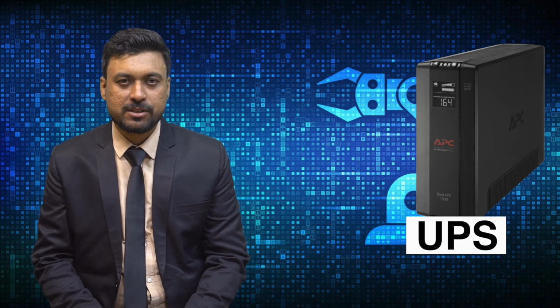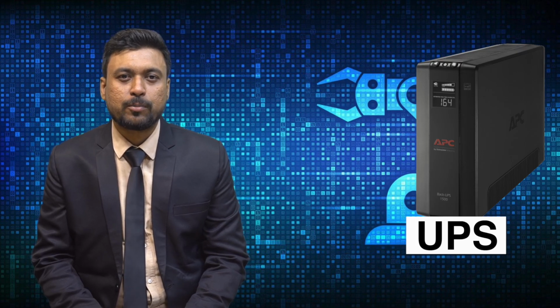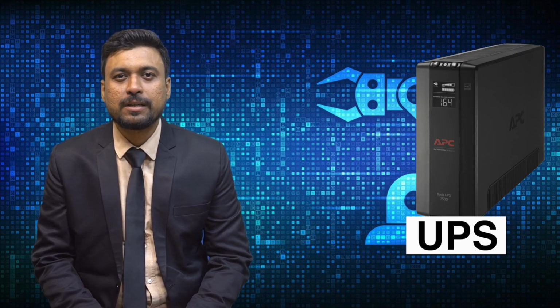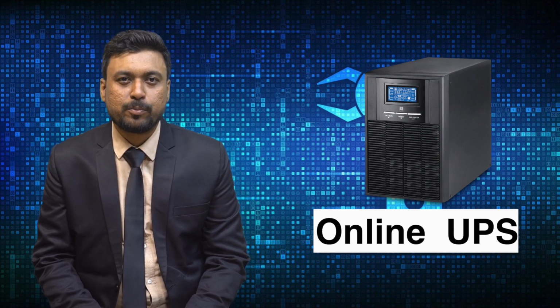Now let's talk about the uninterruptible power supply, that is UPS, an essential safeguard in industrial automation designed to provide backup power and protect against interruptions to ensure continuous operation of critical systems. Online UPS systems operate by continuously delivering power from their inverters, offering seamless protection with no transfer time during a power outage. This design ensures the highest level of reliability for vital equipment.